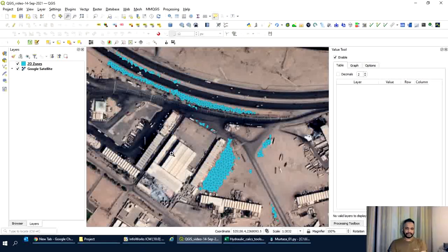The export from shapefile into a raster can of course be done using the inbuilt QGIS tools. But the purpose is to speed up things, do the processing in batch because usually we will have many scenarios and many return periods to be converted from shapefile to ASCII, and also to give the users a bit more control on what needs to be exported, like not the whole shapefile, but maybe depending on the attribute value, the export can be controlled.